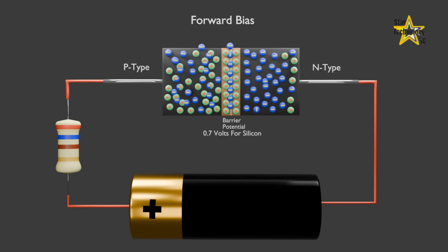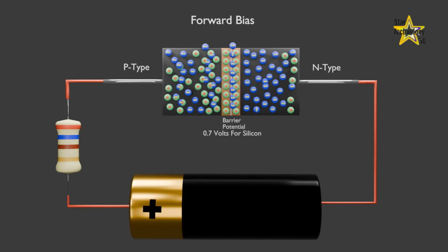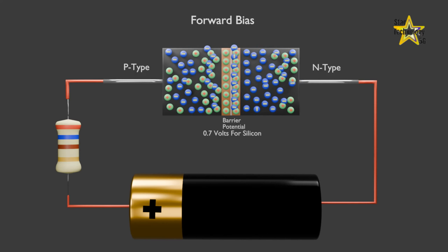With increasing forward bias voltage, the depletion zone eventually becomes thin enough that the zone's electric field can't counteract majority charge carrier motion across the p-n junction, consequently reducing electrical resistance. The electrons, or holes, which cross the p-n junction into the p-type material, or into the n-type material for holes, will diffuse in the near-neutral region.